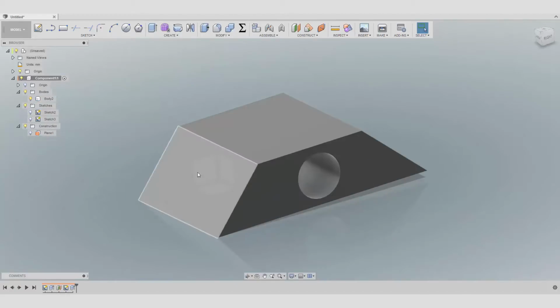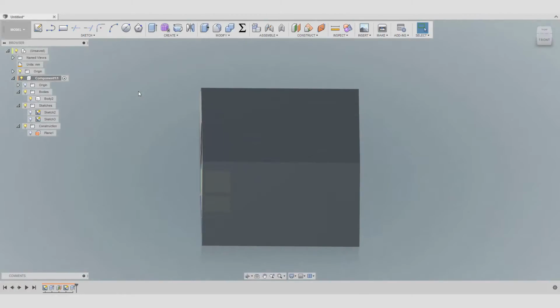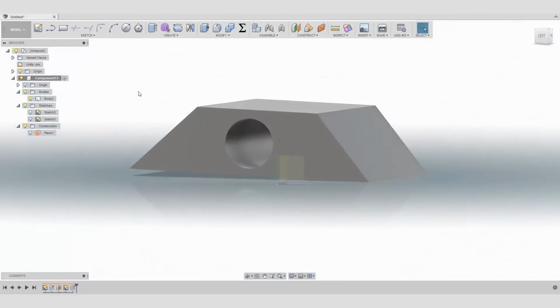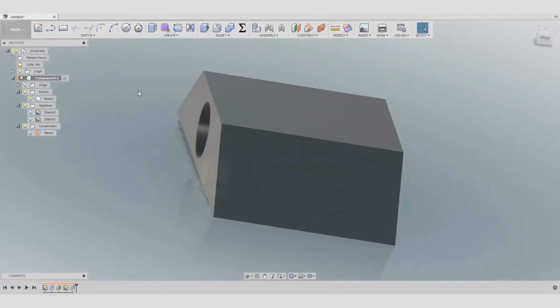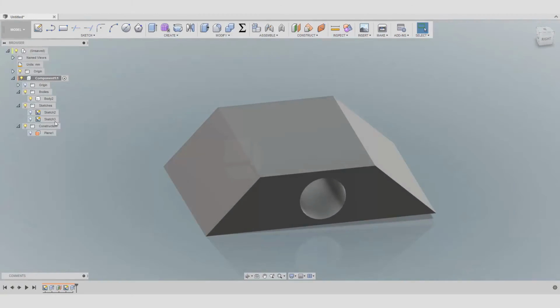If you already have a plane, you just move the plane and that's it. You don't need to move the sketch. But if you don't have a plane, you can just redefine the sketch wherever you want. And yeah, so I think that's basically it for now. I just want you to remember that we have this option here to redefine sketch, and you can also move the plane with the edit feature to whatever you want.